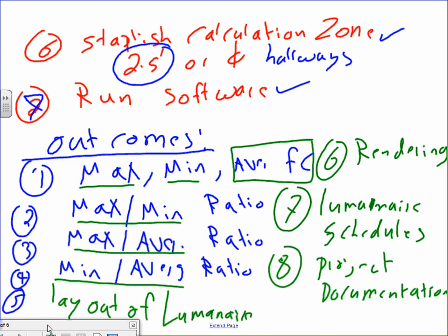After you place them in the model, Karen, you have to establish the calculation zone. The calculation zone, guys, remember the hallways we said put your calculation zone as 0, everywhere else is 2.5. I can't emphasize this enough. You guys are going to be doing the same calculation for me next project. So if you know these steps, I gave you a copy of it. Next time you don't even need Chad's help.